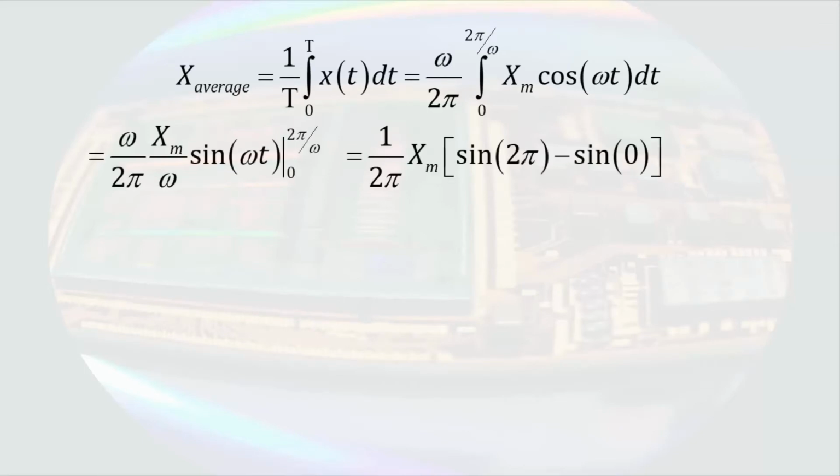I think we should start with the factor of 1/2. In a purely sinusoidal system, both the voltage and current will average to 0. Even though these quantities average to 0, that does not mean the effect they have averages to 0. If we were to connect an inductor, one that has a very small resistance, to the wall outlet, the voltage and current would be 90 degrees out of phase, and the voltage, current, and power would all average to 0. Yet the circuit breaker for the wall outlet still trips. If the average of everything is 0, what is it that had enough of an effect to trip the breaker?